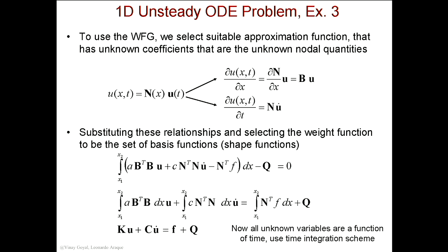We'll plug this in now into the weak form. And when I do that, this is what I come up with. You guys can check it at home. And finally, I get my value for K bold, my value for C bold, and then I get my forcing function here. This can be a function of time, by the way. My distributed forces. What if I have a wing and the pressure, the lift is changing over time, right? I should be able to model that too. So you can have Q, F, or the pressure on the structure vary as a function of time.